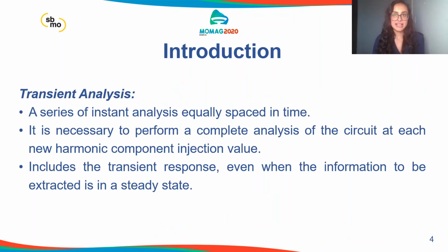In the transient analysis, the solution of a circuit requires a series of analyses equally spaced in time to obtain the complete response of the circuit in a time interval. The solution depends directly on the initial conditions of the circuit. To analyze a power system circuit, considering the variation of the amplitude of the harmonic components, when using traditional transient simulation, it is necessary to perform a complete analysis of the circuit at each new harmonic component injection value, making the process more